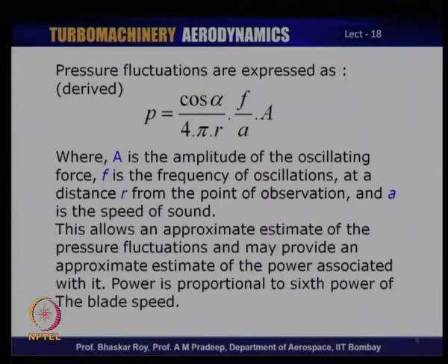Now, as I was trying to mention a little while earlier, the power that goes with the noise is proportional to the 6th power of the blade speed. So, a slight increase or decrease of the blade speed would strongly impact the noise and the power associated with the noise. So, we have to keep an eye on that blade speed, or the relative blade speed, very stringently if you want to keep a check on the noise that is emanating from the rotating blades.